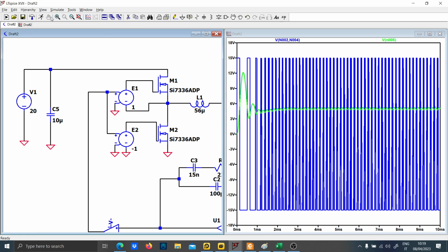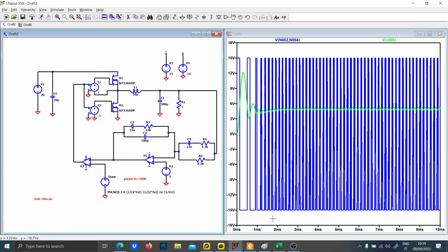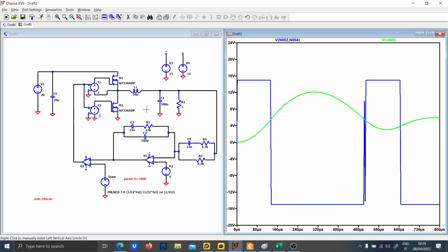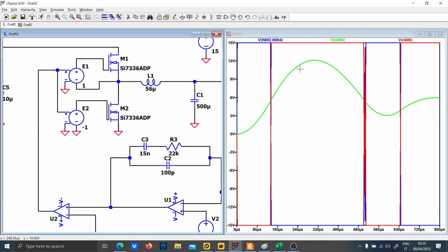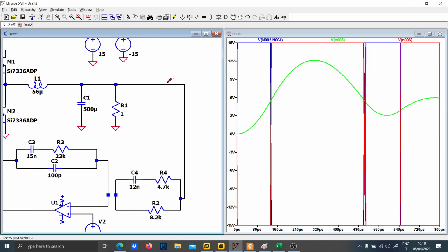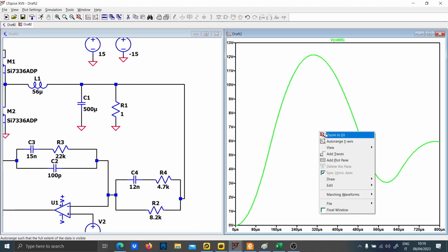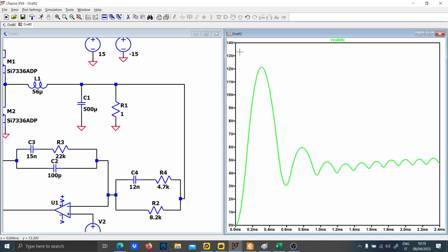As you can see, the synchronous configuration is better, not only because it dissipates less, but also because it is working more properly. It is true that the duty cycle of this is negative, but the duty cycle of this will be high, and so you are forcing the low side to conduct current, and the buck converter is never off. And so you now see the proper oscillation of the transient of the buck converter.